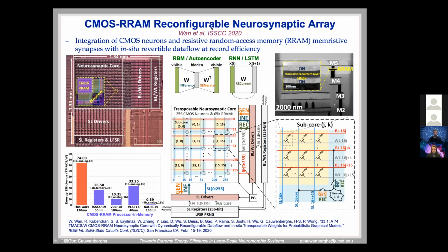With the layer 1, so Raj, and Ram, etc., the whole team, and this was in collaboration with Philip Wong's group at Stanford, and also with the collaboration at Tsinghua and that whole team here. We showed, in fact, we have an arXiv paper that now demonstrates a 48 core system of the same, with millions of synapses and tens of thousands of neurons. All doing just AI. In fact, we have demonstrated all the way from MNIST to CIFAR 10, all implemented with those crossbar arrays of synapses and neurons.